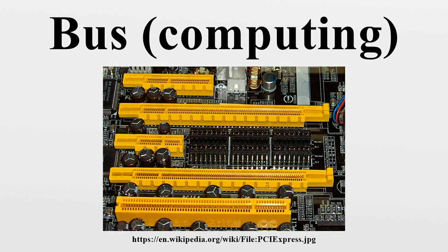Still, devices interrupted the CPU by signaling on separate CPU pins. For instance, a disk drive controller would signal the CPU that new data was ready to be read, at which point the CPU would move the data by reading the memory location that corresponded to the disk drive. Almost all early microcomputers were built in this fashion, starting with the S100 bus in the Altair 8800 computer system.